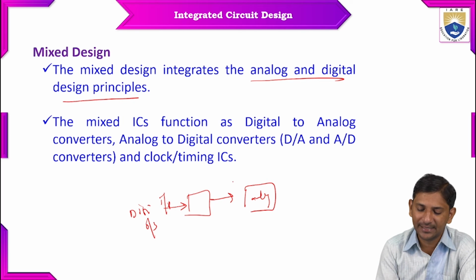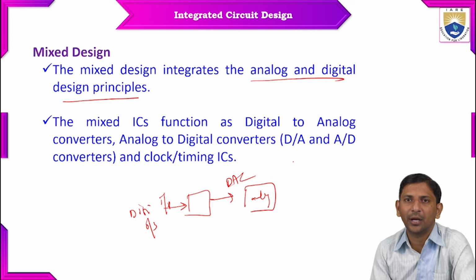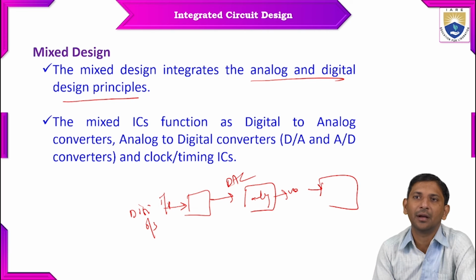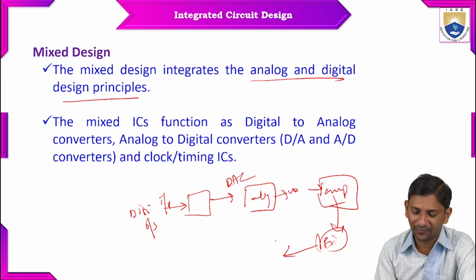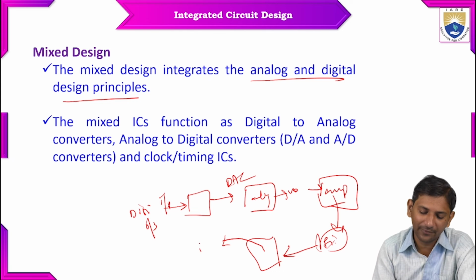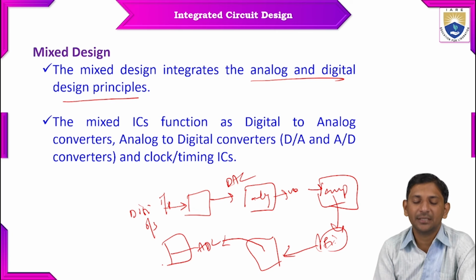By doing that ADC DAC conversion, any such method can be used to convert digital pins into analog voltage. This voltage will be given some amplification, modulation, or any operation. Then after that amplification process, we go for some filtering operation. Again, that output is in the form of voltage now. This voltage cannot be stored in any digital storage. So again, we will apply an ADC, which converts it into a digital output.